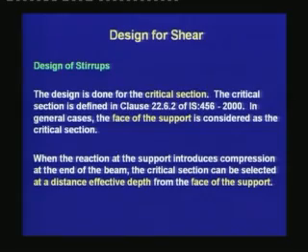Once we traverse from the middle of the beam towards the support, for a uniformly distributed load, the shear increases. Now, the shear at the face of the support can be used for the design, because once we enter the support, then the depth of the section is large and we do not expect a shear failure.